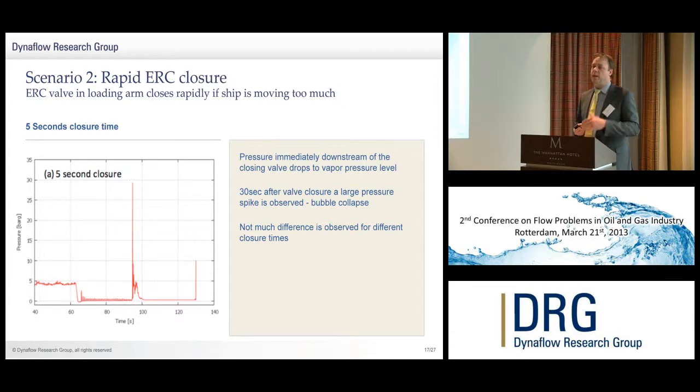Because what would happen at these relatively high points at the bridges and at the siphon, the vapor pressure would be reached for the naphtha. So the high points would be completely vaporized, and then when the system seemed to be more or less coming to a rest, the pressure would go up again, because of either the back pressure or the continuous operation of the pump, and the bubbles would collapse, causing these enormous high spikes.